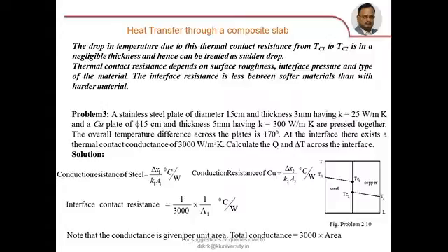Under such circumstances, instead of a copper bottom increasing the rate of heat transfer, due to this existence of thermal contact resistance, it will reduce the rate of heat transfer and lead to more consumption of fuel for the cooking process. So that is why when you buy a copper bottom vessel, you have to go for a branded one which is assembled in a factory, taking care of all these factors which we have discussed with reference to the thermal contact resistance.